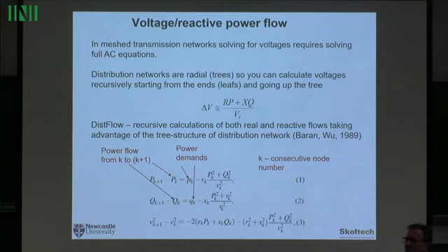What is your opinion if you ignore that last term? Then you don't take into account transmission losses, but remember again in the distribution network resistances are higher, right? So you can get away with neglecting transmission losses in the transmission network because resistances are low. Distribution network,